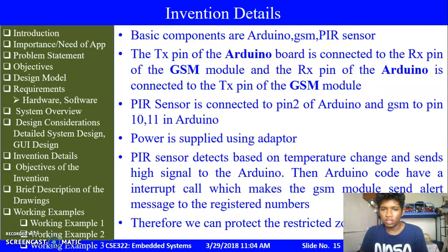You get a variation in the infrared radiation, like in a graph, and the sensor basically gets to know that there is a difference in the plot. The basic temperature will be at a constant level, and when someone comes, the graph will be altered. So depending on that, it checks whether there is any presence of an intruder or a human or anything else in that zone.